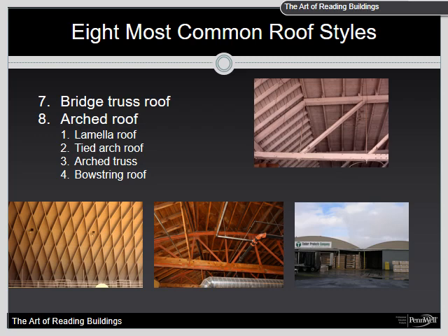Building owners often remedy cracked or split bottom cords by adding a tension rod that spans the bottom cord and is affixed to its end or to the abutment wall. In this case, the remedy has converted the ridge arch to a bowstring and should be treated as such.